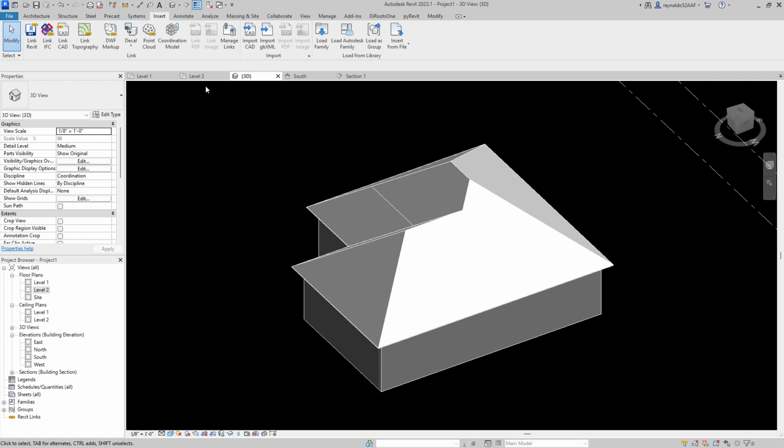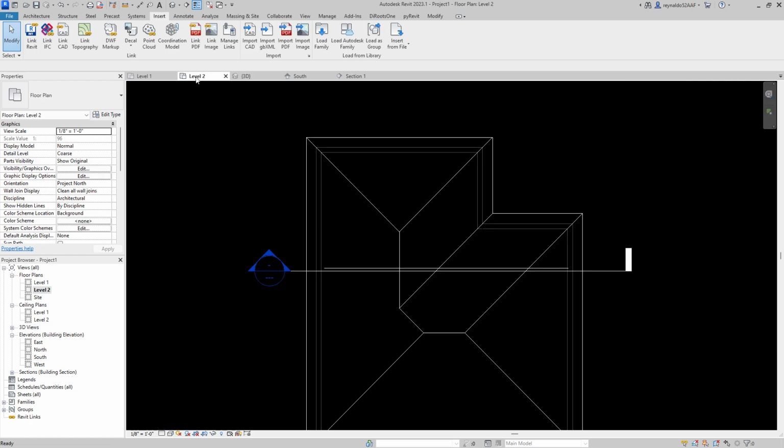So if I were to go back to my second level, basically all the roof trusses from this point to this point will all pretty much be the same. And then once you start getting the profiles for here, you would have to draw another one from scratch, adjust the profile, and then just copy each of the following ones, and then slightly adjust the confines of your top chords so that they meet the restrictions of your roof lines by modifying the truss profile.